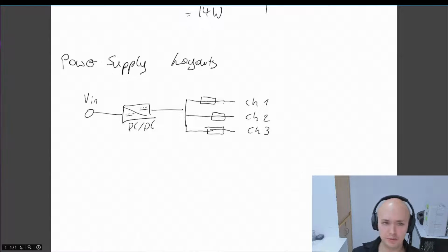Of course, that design brings a lot of implications with it. First of all, we will need to build a massive switching regulator. Very interestingly, they are pretty available currently. On DigiKey, I found a part which is rated for 10 amperes, 12 volts, for $1.80 in single quantities.